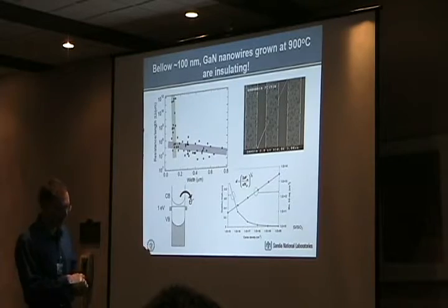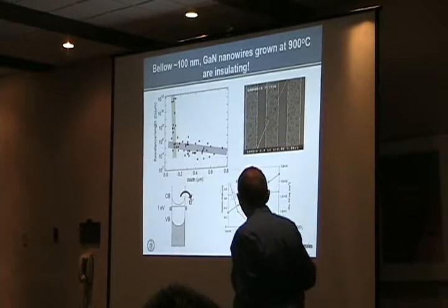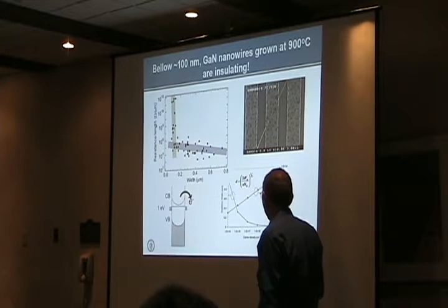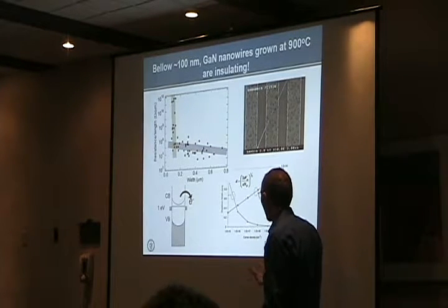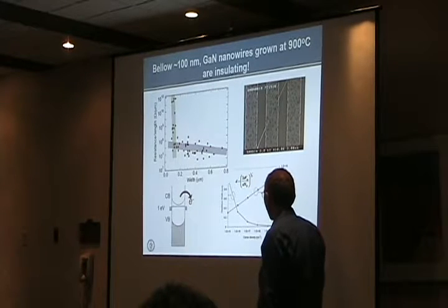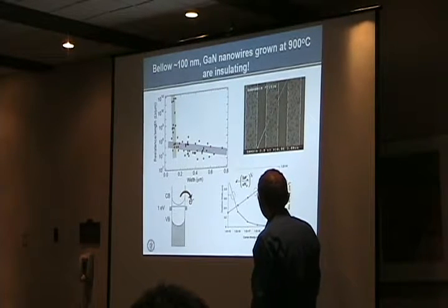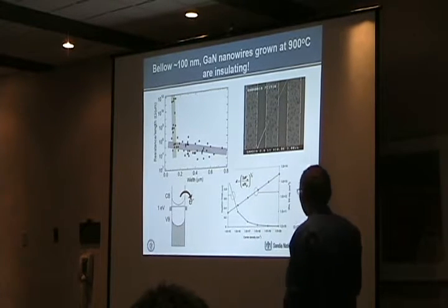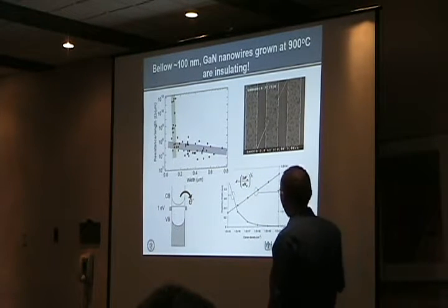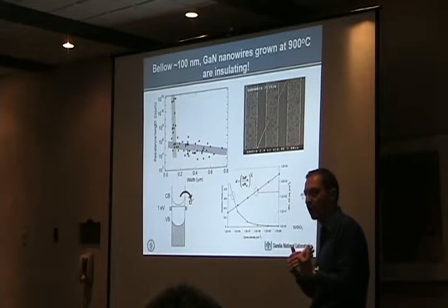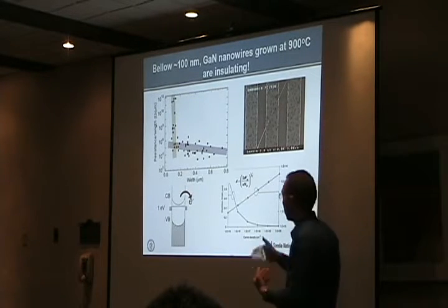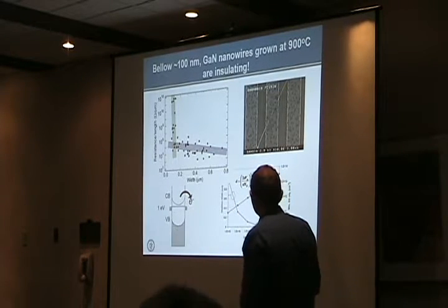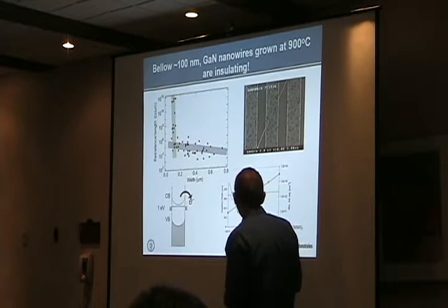What you see here is the plot where I plotted the electron concentration density, which in MOCVD-grown undoped gallium nitride is typically something like 1e17. And then I've plotted here the minimum surface state density per centimeter squared required to accept those carriers. Because what you have is carriers in the bulk, they find some surface state and go into the surface state, right?